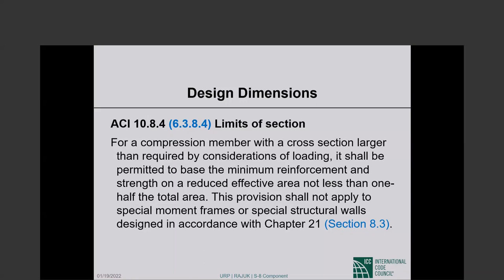You taper the reinforcement off, and when you have reached 1%, you switch to an even lower concrete strength. So at the very top of the building, we typically end up with 4,000 psi concrete and 0.5% reinforcement, not 1%, because the column in those parts will be much larger than needed for the loads.